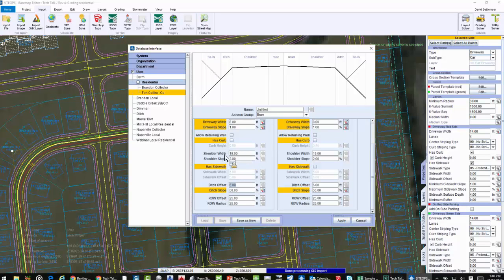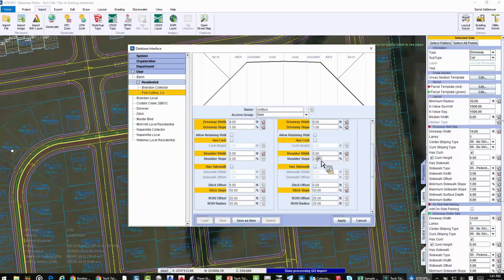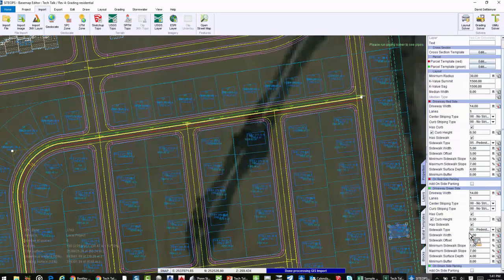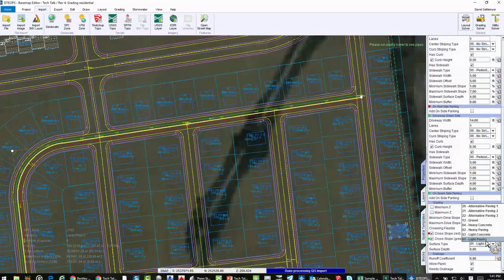Let's go with a shoulder width of 5 and 5, and maybe here it's a 10% slope, a little steeper than on the main pad. So at that point, however I define that cross section, that would be the point where we can do that. What happens on the top of that roadway or that pad can be a road or a rail, and what a lot of people will do on the rail is come back in, because it's mainly gravel instead of asphalt. They set their gravel base for that, so it gives a cost.